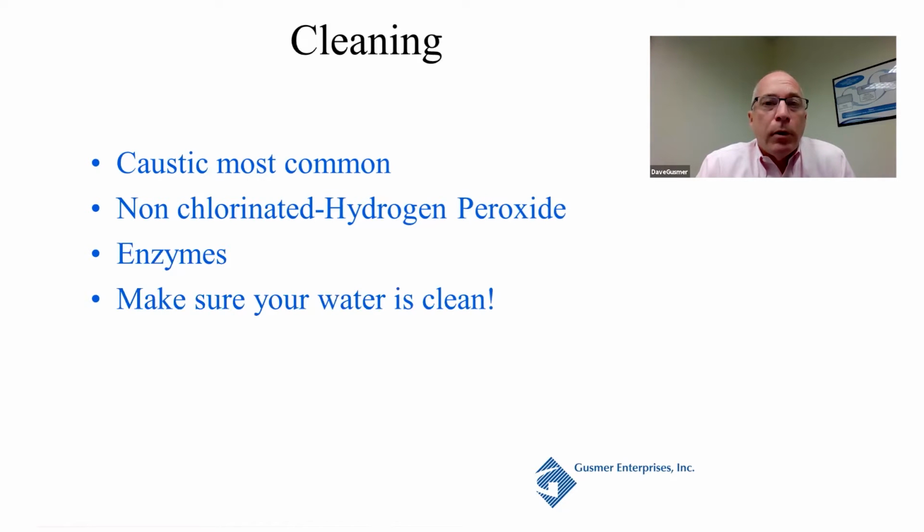Important point here is about your water. We have found that quite frequently what's plugging the filter is not dirty wine. It's your water on site. If you have very poor city water or very poor well water, you may need to get some water treatment prior to the filter to make sure that we're maintaining the cleanliness.